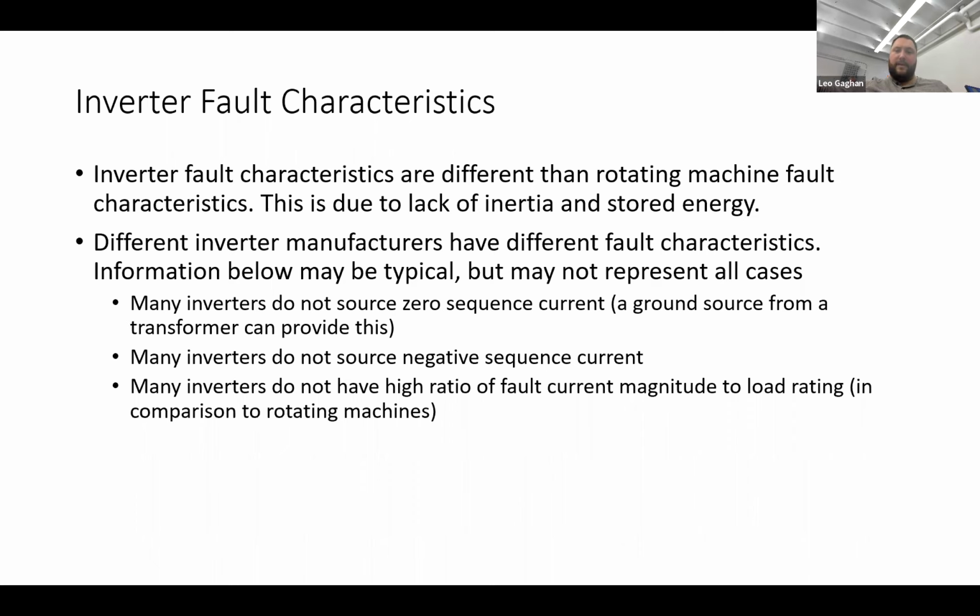So that's one myself. It's not a big deal maybe right here on the system, but I am curious to see how, as these inverter-based generation sites really start to outweigh the rotating machine-based generation sites, how that's going to affect the transmission system, where most transmission directional relays may not start to work the way that they had been originally designed.